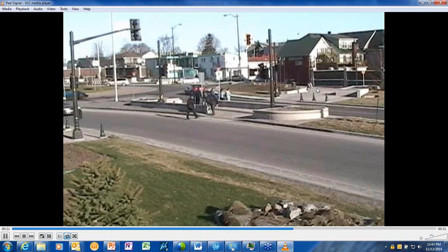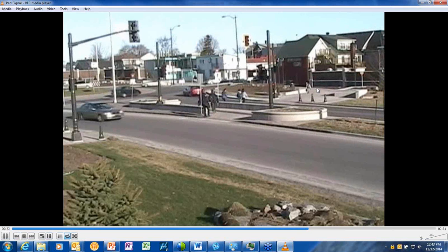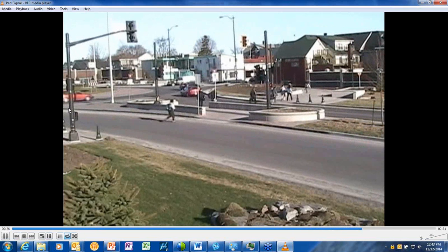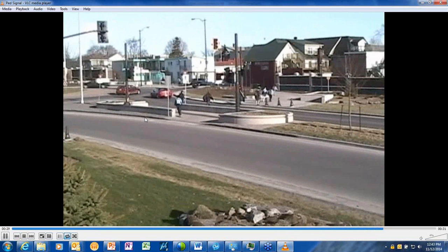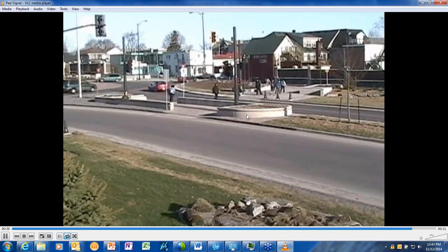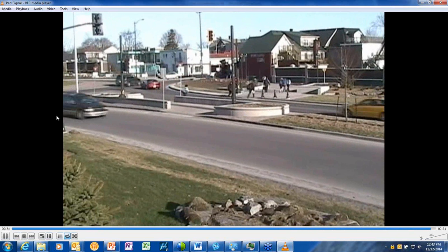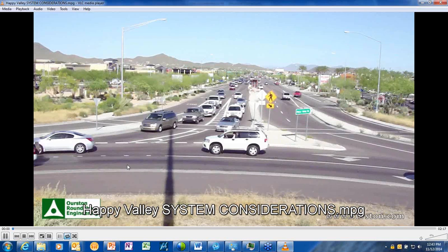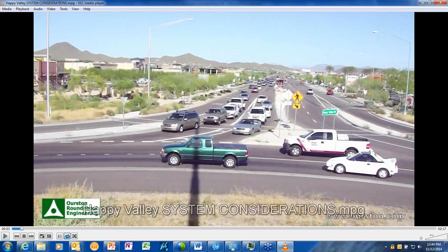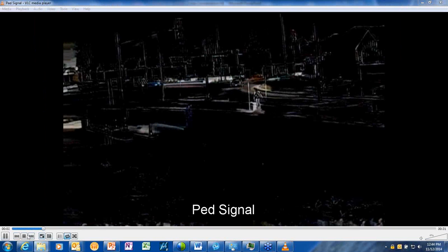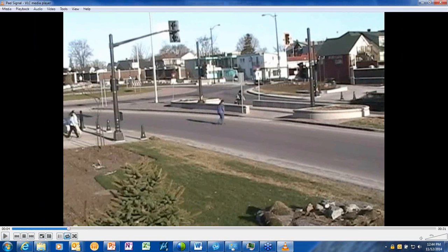And then if the light changes, the drivers are stopping for the light and wondering why there are no pedestrians in the crossing. So the better technology to combine with this is what the British have done, and that's to install a gap-out mechanism, whether it's microwave, infrared, or tactile strip.